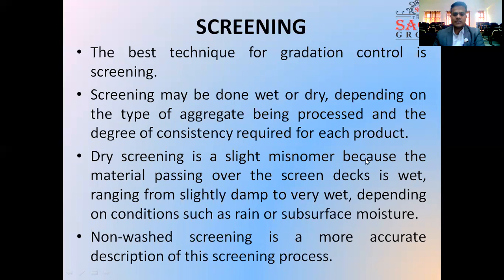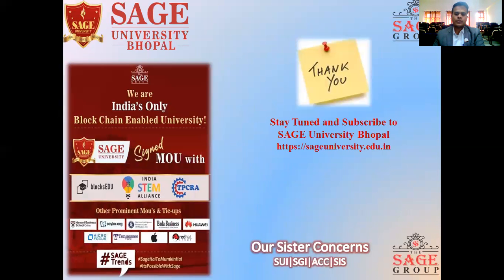Dry screening is a slightly misnomer because the material passing over the screen is wet, ranging from slightly damp to very wet, depending on conditions such as rain or subsurface moisture. Non-washed screening is a more accurate description of the screening process.